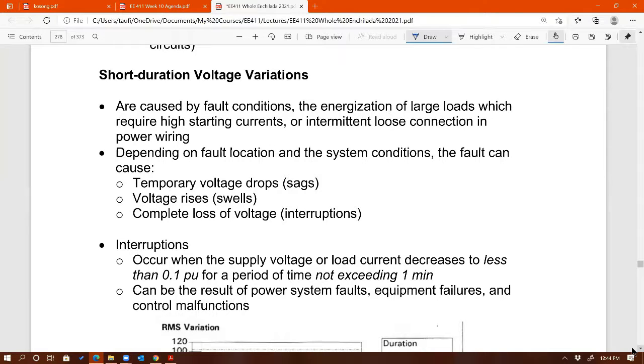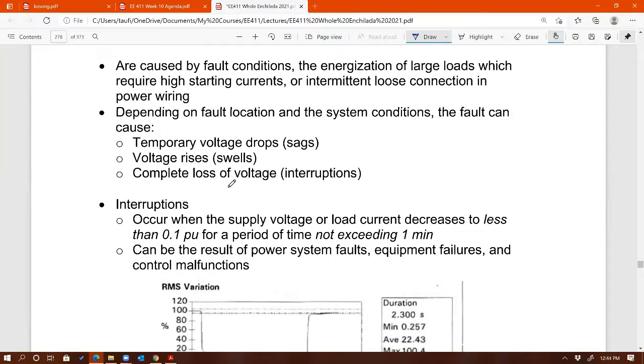Yeah, that clears it up. Right. I don't know, but I've seen it before. I think nowadays it's pretty good. I don't remember where, maybe when I was in Atascadero. Anytime I turn on AC, I could see quickly that the lights dim a little bit, right? That's coming from the starting current of the motor being used by the air conditioning. I don't know if you've seen that before, that the light dims a little bit when you turn on the AC.